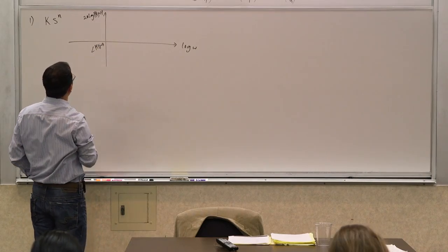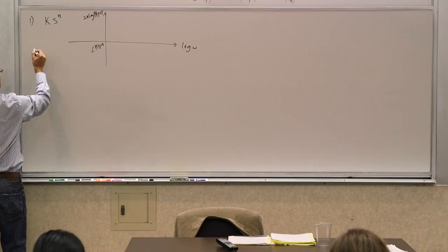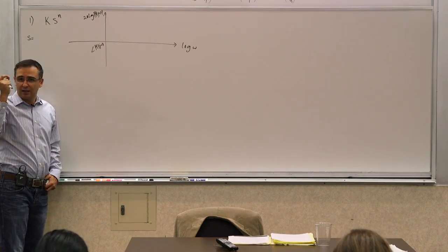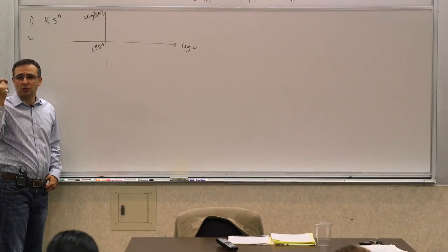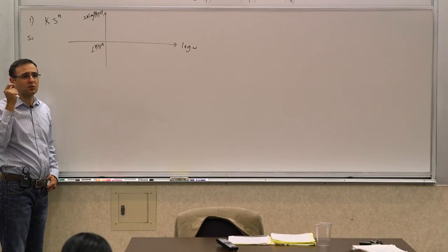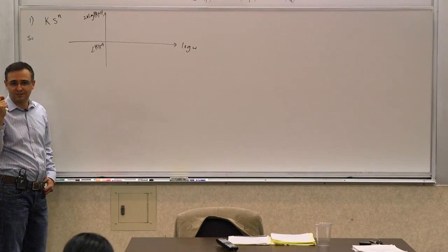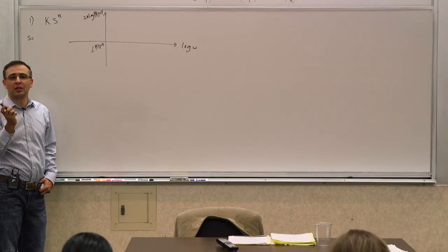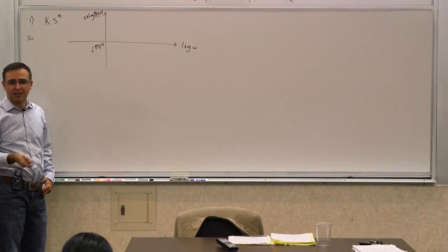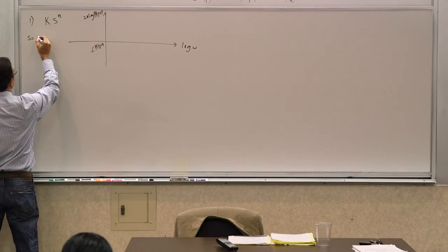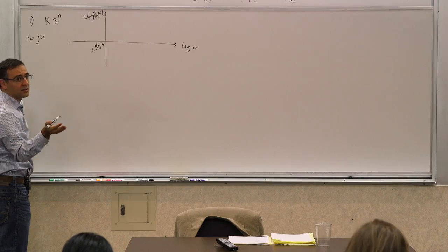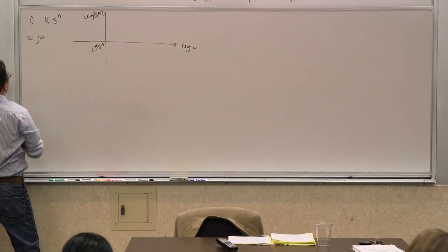Right? So how does that look like? Well, let's look at it. Whenever you're looking at Bode plots, you're looking at specific kinds of s, right? You're looking at sines and cosines, which corresponds to s being j omega. More accurately, you're looking at unity magnitude exponentials, e to the j something, as stimuli, which can be written as sums of sines and cosines. So s equals j omega.